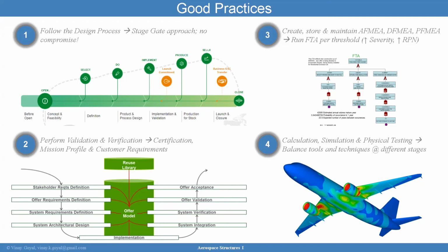So it's very, very important to be as detailed as possible, as negative as possible, right? In terms of trying to come up with every single thing that can go wrong. And again, for those items that represent a high severity level and or a high RPN, you must take certain actions just to be able to mitigate the impact of those line items.